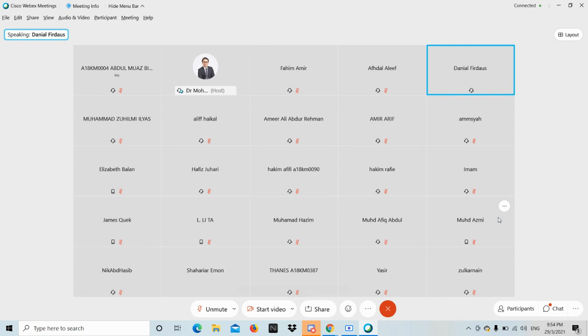And then, what are the disadvantages of having a shorter stroke? I guess the low end torque or something. Yeah, definitely the low end torque. If you relatively compare a long stroke and a short stroke, a longer stroke would have better combustion because the compression of the mixture is much better compared to a shorter stroke.